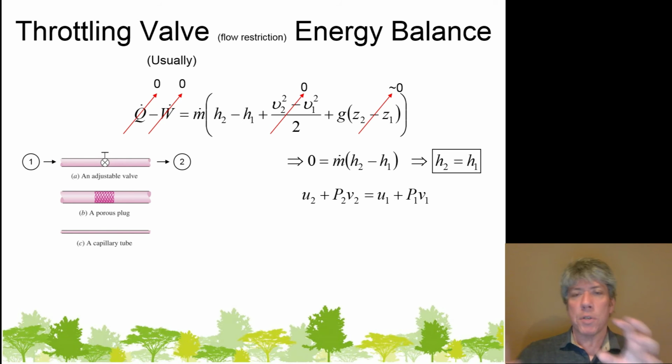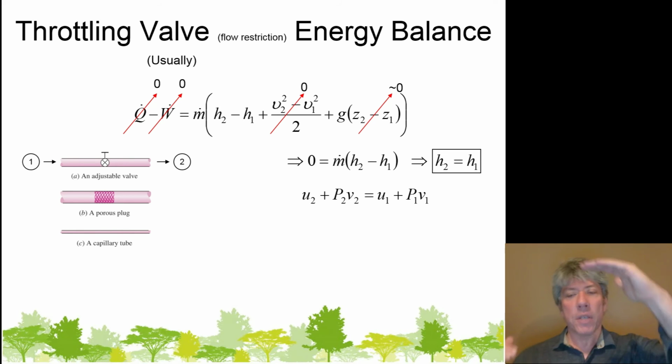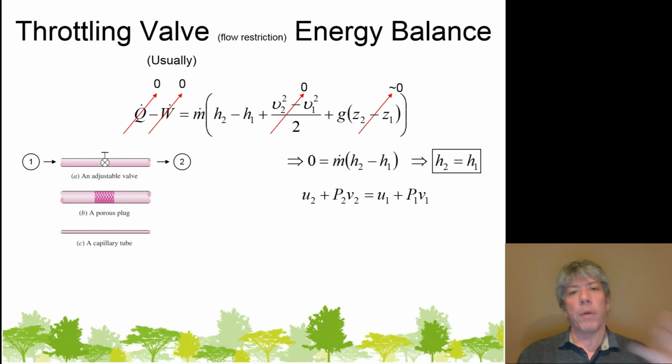So while the temperature may go down and therefore the internal energy or the thermal energy goes from a high level at U1 to a low level at U2, that's compensated for by the flow energy. The flow energy leaving is greater than the flow energy entering. So just because the temperature goes down doesn't mean we've lost energy. In fact, what this says is we've lost zero energy whatsoever. And that may seem counterintuitive because a lot of you feel that temperature represents how much energy something has, and that's not the case. There are other forms of energy.